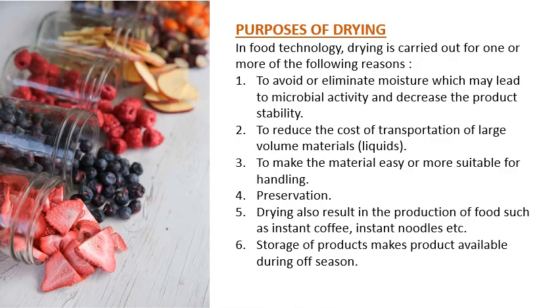Now, the purpose of drying. Why do we need drying? In food technology, drying is carried out for one or more of the following reasons: to avoid or eliminate moisture which may lead to microbial activity and increase the product stability, to reduce the cost of transportation of large volume materials, and to make the material easier or more suitable for handling and preservation. Drying also results in the production of food such as instant coffee and instant noodles, and storage of product makes product available during off season.